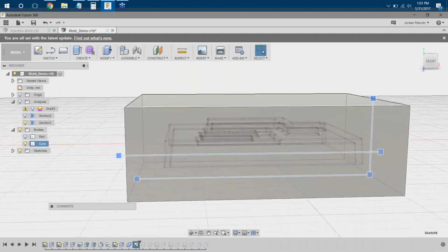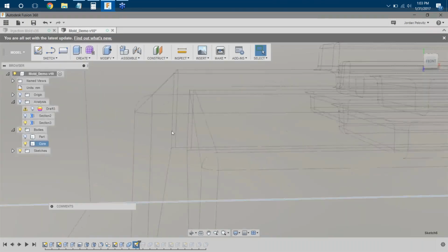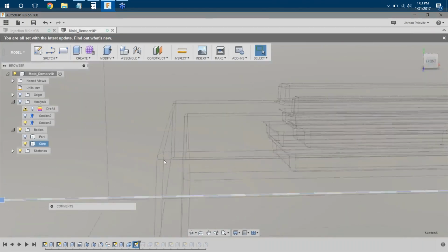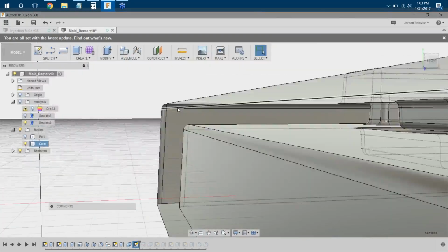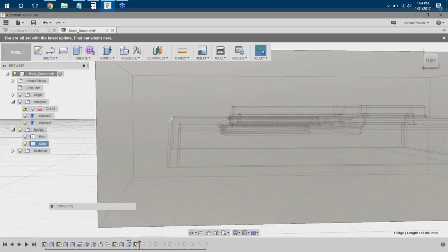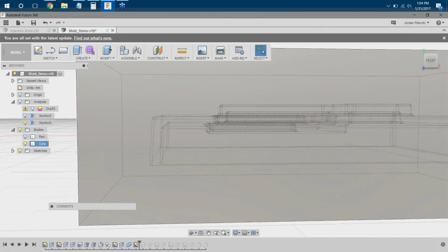And then also, if you add a parting line on a fillet, say right about here, when you put two mold halves together, there's always going to be a little misalignment. So you want to be careful not to put a parting line on a fillet, because if you do, it'll be more obvious where the misalignment occurred. By putting it on the bottom, away from any fillets, it's less obvious if that should happen.